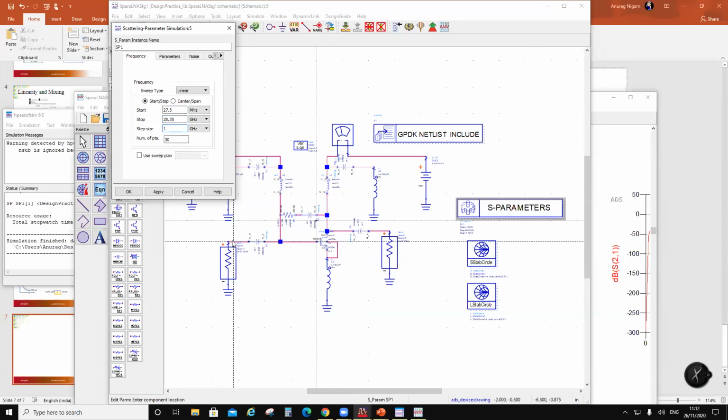Okay, broadband amplifiers. In broadband amplifiers, there are two options for you. One is the matching you do broadband. The other is the traveling wave amplifier. So these are two different concepts, right? And in traveling wave amplifiers, waves travel in two directions from any source. One is the forward, the other is the backward.